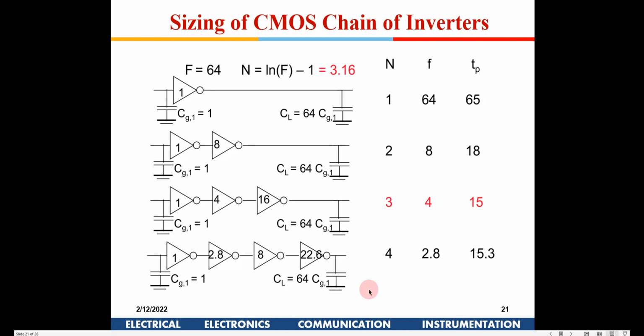Yeah, if you see here, the CL would be slightly modified. I got your point. Obviously, here you will find CL is coming from this transistor also. Here it is not coming, so that aspect has been neglected. And this propagation delay is for the complete chain, right? Yeah, from here to here. Okay. And how was this formulation arrived at?